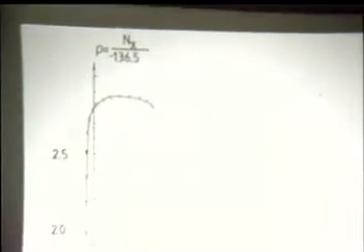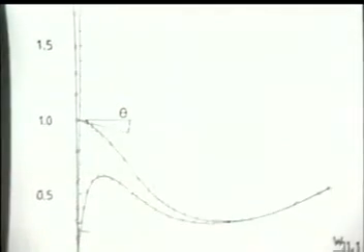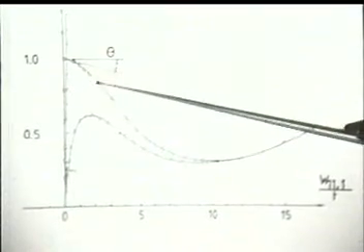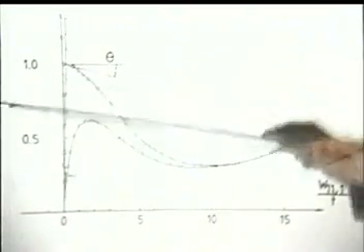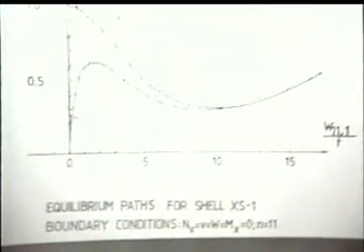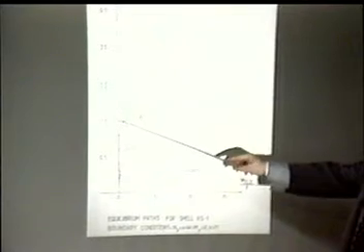So bifurcation of the perfect system occurs at 1. With the asymptotic method, we describe the behavior close to here. If you really want to know how accurate your asymptotic method is, you have to go to higher order models and calculate the post-buckling curves with a code where the errors are not of order c bar, but higher. And then you can compare the two.